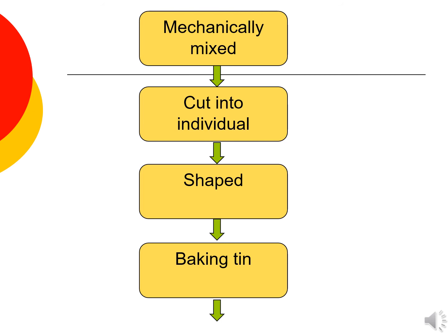Air pressure in the mixer headspace can be controlled to keep gas bubbles at the desired size and number. Typical operating regimes are pressure followed by vacuum, and atmospheric followed by vacuum.